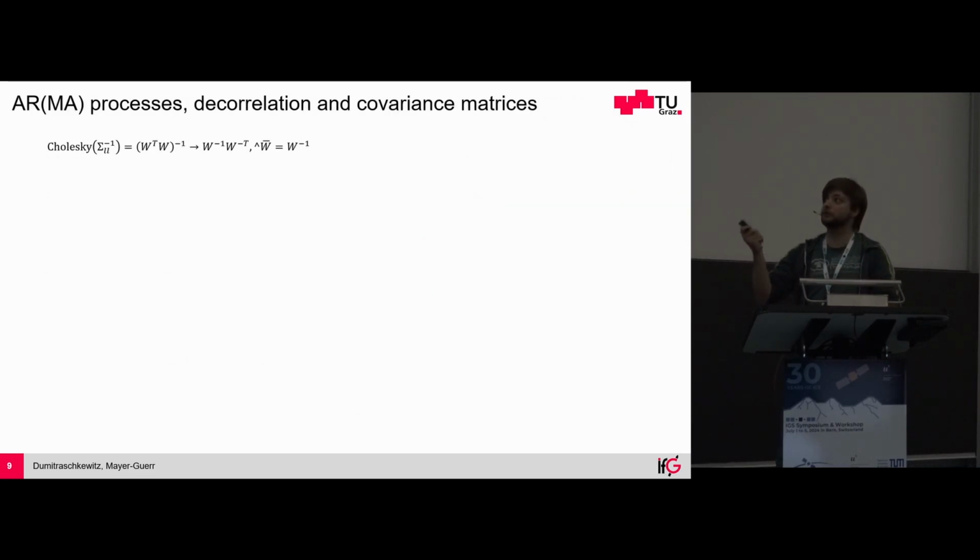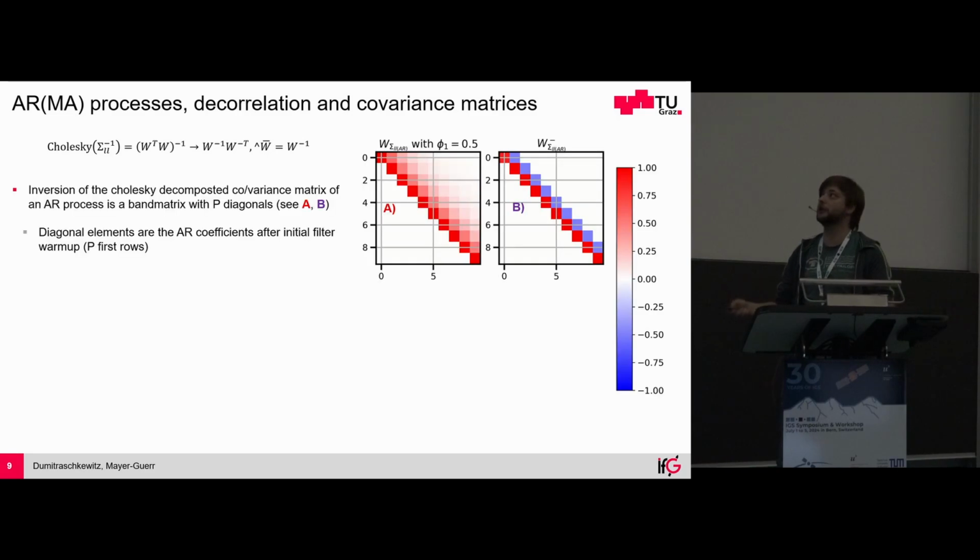First of all, we don't take any correlation between observers and satellites into account. We don't take any correlations between phase and code into account, and only temporal correlations. The good thing is, when we look at the decorrelation matrix in a blockwise manner, for any epoch I, we can just select the diagonal elements for the decorrelation, and for any other lag higher than I plus 1 or I minus 1, we can just use the upper diagonal elements, which would lead to accumulation then to looking like this.